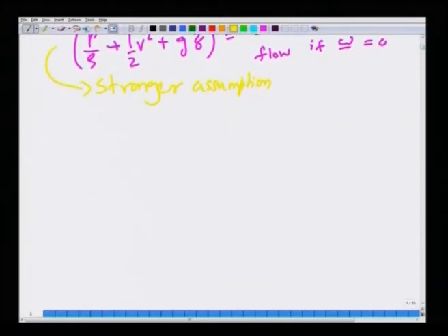We also pointed out in the last lecture that irrotationality, although being a kinematic assumption, is more likely to be seen at higher Reynolds numbers when you are far away from solid surfaces. So, we can assume the flow to be reasonably irrotational when the fluid flow is happening at higher Reynolds number, but close to the solid surfaces rotational effects become important. We can imagine the solid surfaces to be sources of vorticity, and the vorticity will be confined close to the solid surfaces, but far away from solid surfaces at higher Reynolds numbers the flow is largely irrotational.